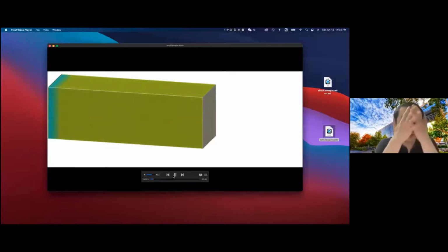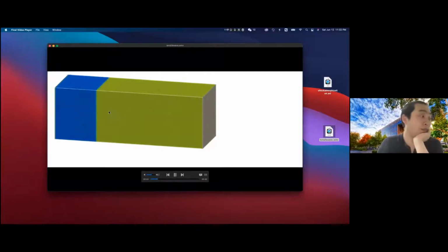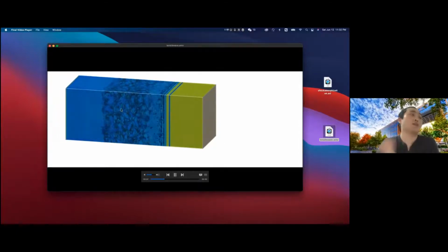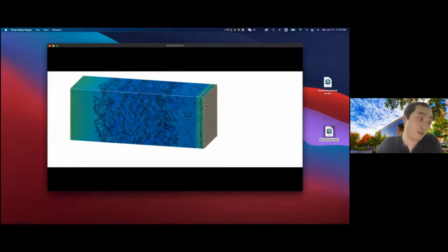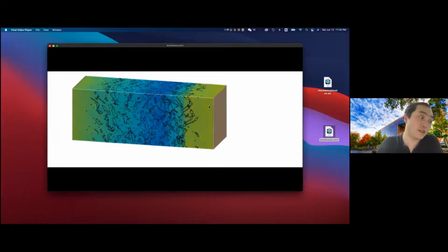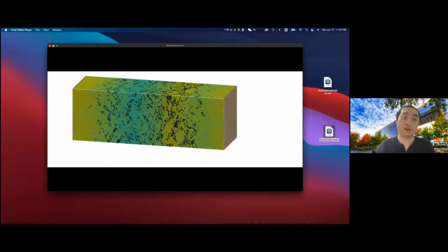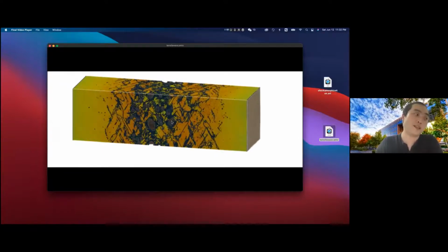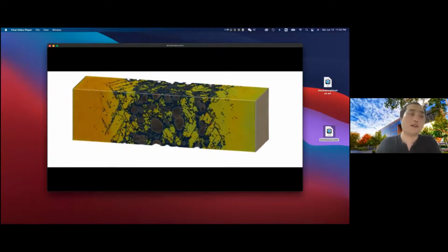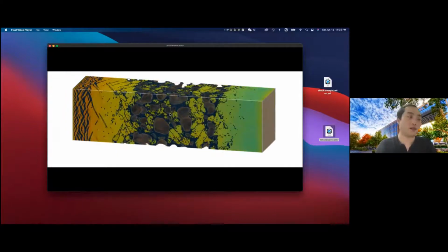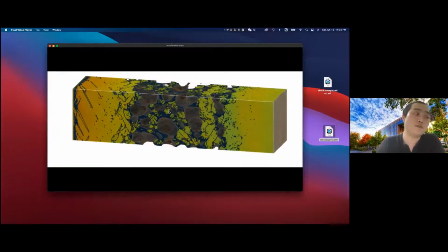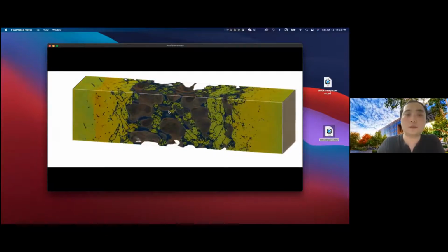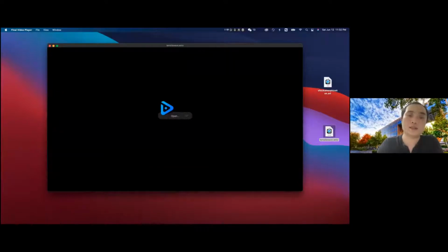So if you look at the video, the shock front is here, right? It's compressed the material along the way and generated lots of defects. And when the compressive wave reaches the back surface, which is the free surface, the stress will be flipped into a tensile wave. And a tensile wave is destructive. Ultimately, it leads to void nucleation, and the void will grow and eventually coalesce. So this is the dominating mechanism of ductile failure in materials under dynamic tensile loading conditions.